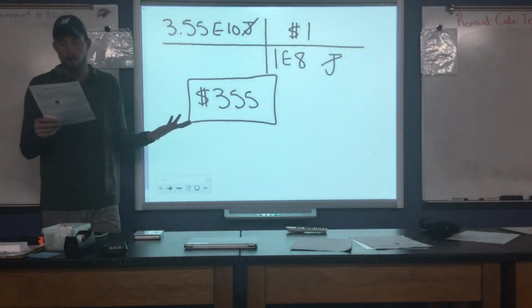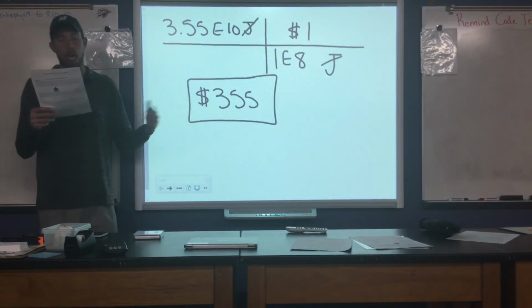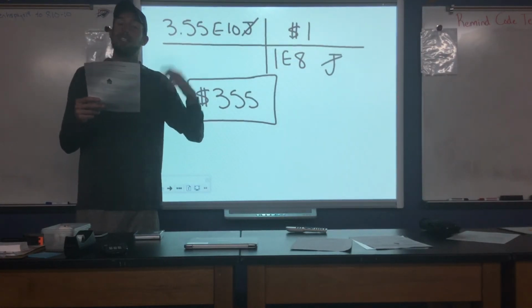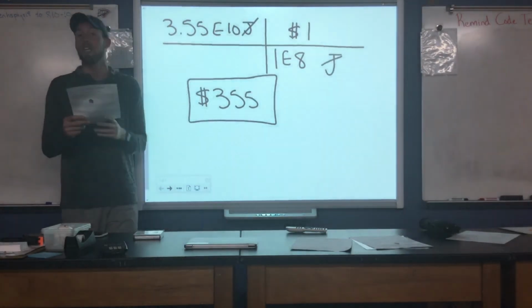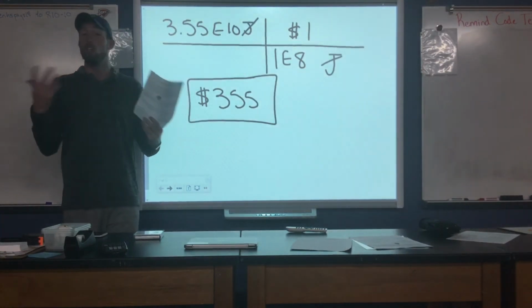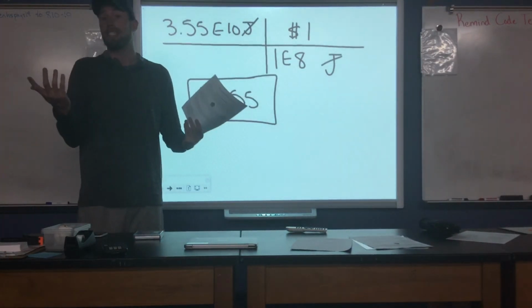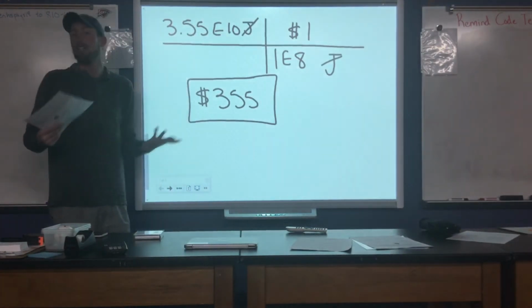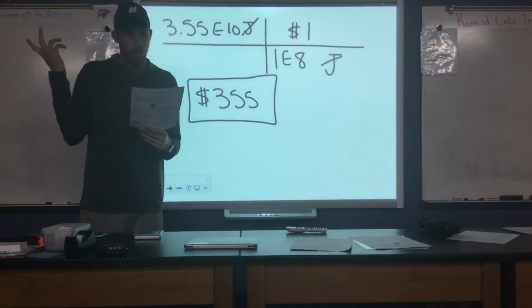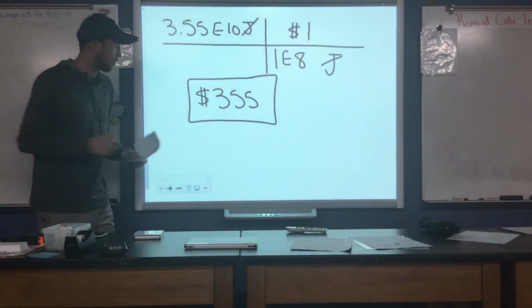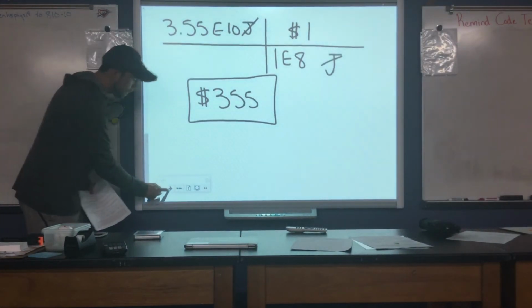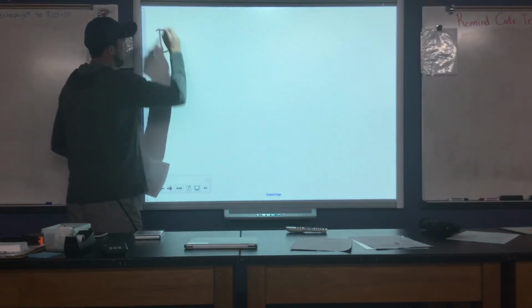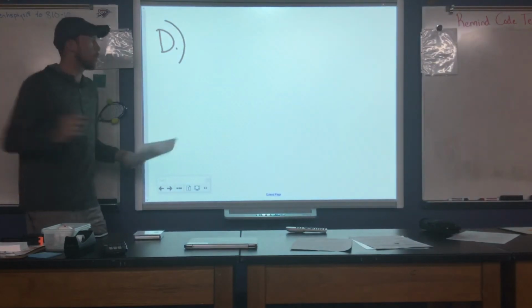Now there are 3 different models there. I'm just going to choose one. We've got Model 1, which deals with an actual pocket of air, Model 2, which has a pocket of argon, and Model 3, which has a pocket of krypton. Oftentimes, noble gases or inert gases are good materials to use for these types of energy-efficient windows because they're very non-reactive. So let's just choose Model 2, argon. Really, we could choose any one of these, but let's choose Model 2. So here in Part D, what we'll do is we'll look at finding the new heat transfer rate for this other model.